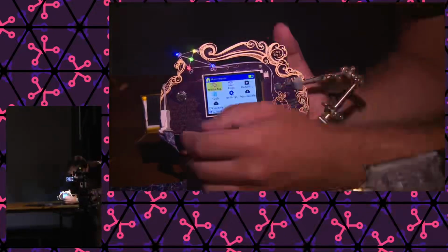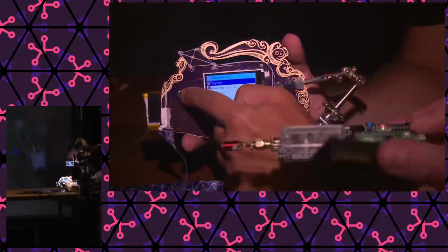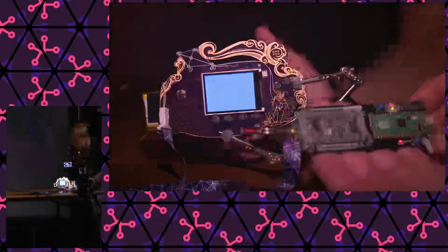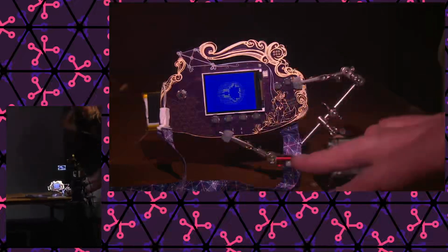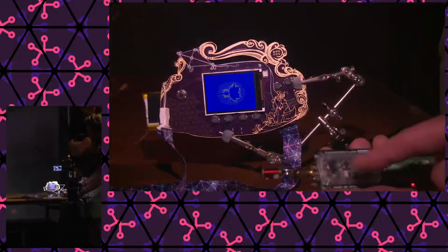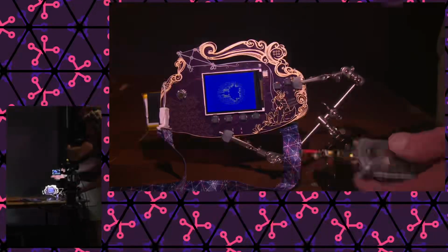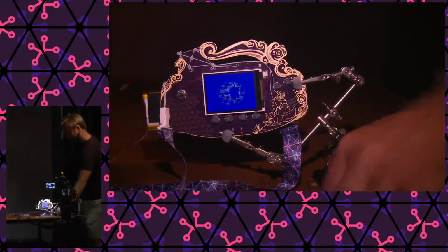And just to maybe quickly say something about the hardware, this is very similar to what we described. This is just a battery pack. This Raspberry Pi is for controlling the logic. This is the coil. It just builds up a charge in here and discharges it very quickly through that coil right beside the chip itself. And that's how you're introducing the fault.